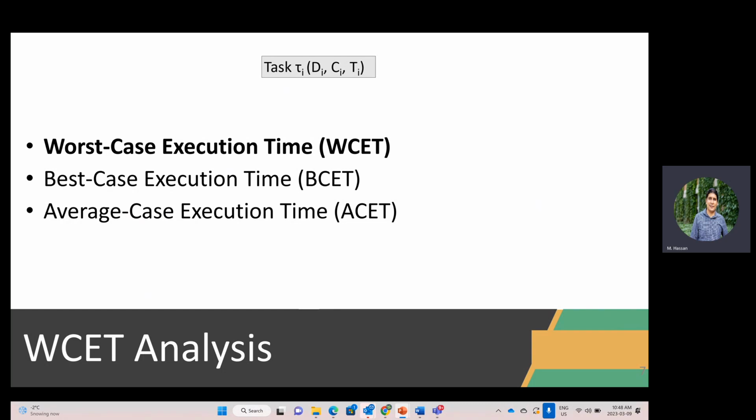And we differentiated between, so in lecture 0 and 1, we put multiple definitions of embedded systems as opposed to general purpose systems. One of them was what metric do you care about? We said mostly embedded systems, especially safety critical ones, care about the WCET, worst case scenario, while average case is more of a concern to the general purpose systems, right? And then we took one step further and said in modern embedded systems, and we give the example of modern automotive, for example, also average case is of importance because we have what we call mixed criticality.